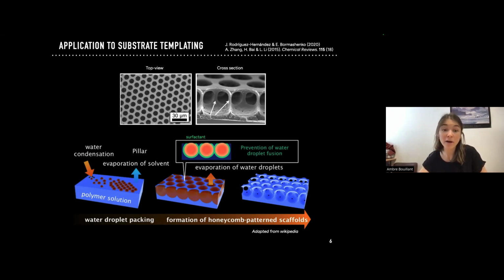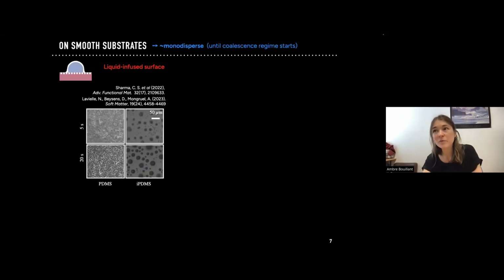And the question is now how the surface rheology affects the condensation process, and this is something that I will try to answer in this presentation. What interests me is substrates that have properties lying in between, that are neither liquid nor solid. Those typical materials have been quite investigated. For example, people have looked at condensation on liquid infused surfaces, and we see that the condensation seems to be enhanced, eased, since the drops are highly mobile. You can just tilt your substrate and harvest your liquid.